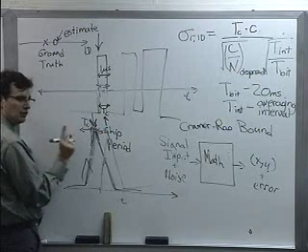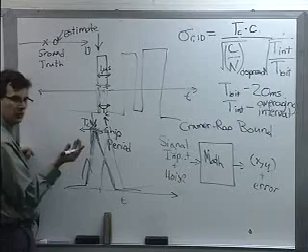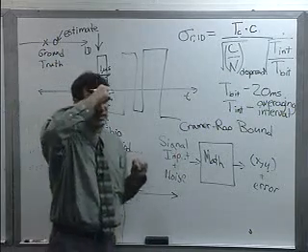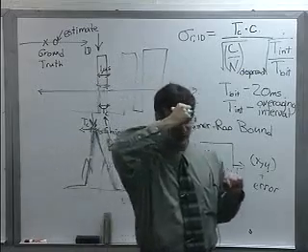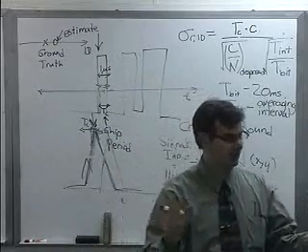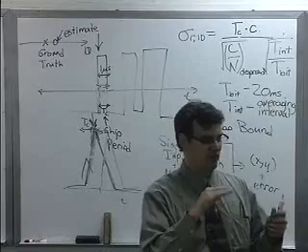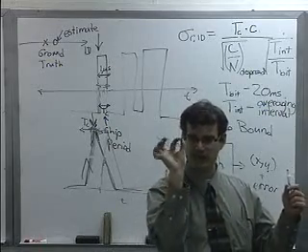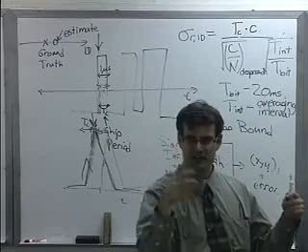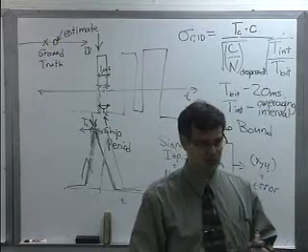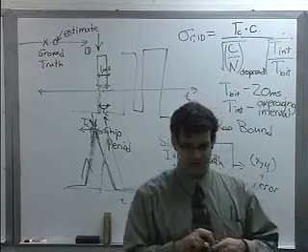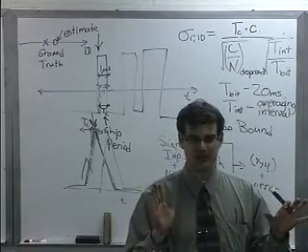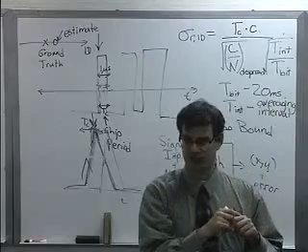But you have to have a really clean signal to have this work. It's just like super resolution techniques in arrays, if anybody's played around with those. It's just the temporal equivalent of that. You assume that you have one nice, clean, multipath-free signal in the time domain. You're trying to pinpoint it very precisely. In array theory, they have super resolution techniques where you've got an antenna array, and you want to calculate very precisely which direction something comes from.